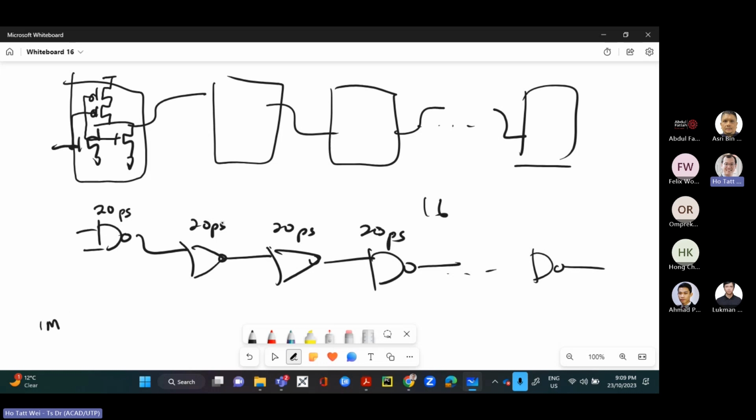If you make 1 million chips with this particular gate, the gate in all the million chips is going to follow a normal distribution with a mean of 20 picoseconds and some kind of standard deviation. This is one standard deviation here, so this encompasses 67%. Out of the 1 million chips, if you look at every single chip and do a histogram, you're going to get 20 picoseconds, and then a distribution that arises from process variation.